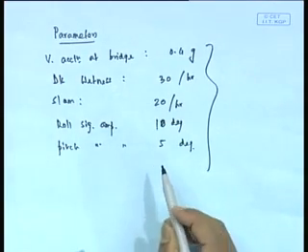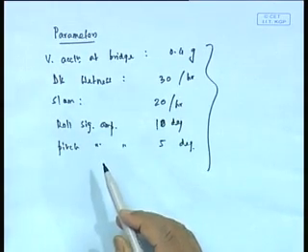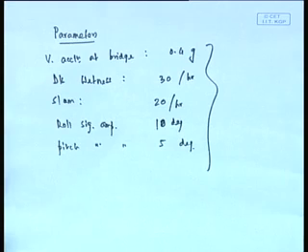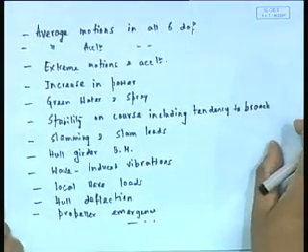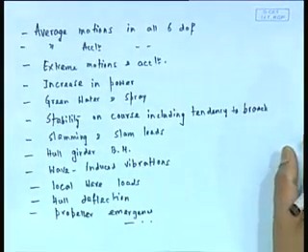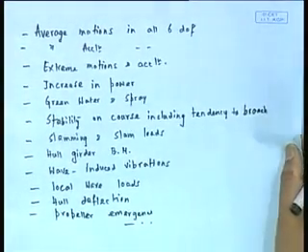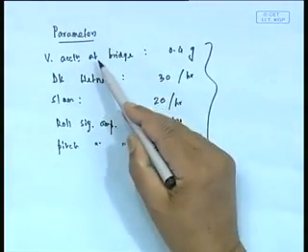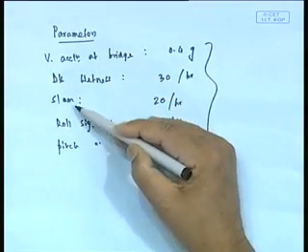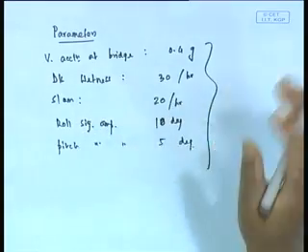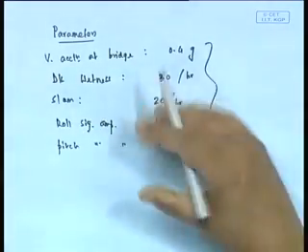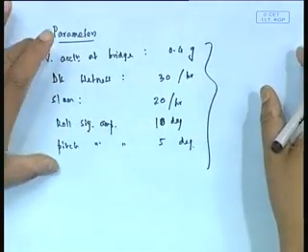Remember one thing, it is not necessary to include all the parameters that we have mentioned earlier. In seakeeping the parameters can be a large number, as we have mentioned earlier. All are not necessary to be mentioned. An operability index or whatever the criteria may be is specified for a few, but typically you will see a common set: vertical acceleration, slamming, deck wetness, roll and pitch. This normally becomes a very important criteria. Most designs will give this.